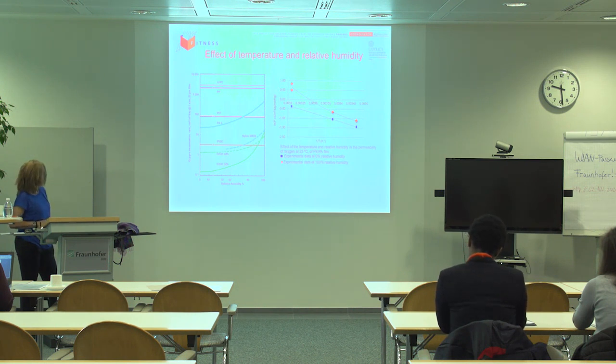Like the PET here in the middle scale, or PVDC that is already in the lower range, so it's a good barrier, and it's a good barrier that does not depend on the relative humidity. So this material keeps the barrier whatever the moisture conditions of use.